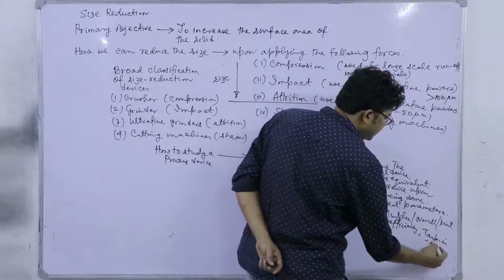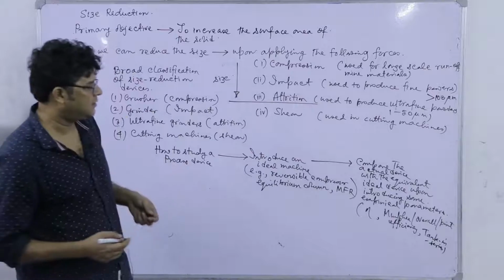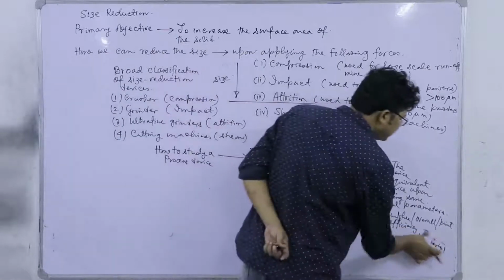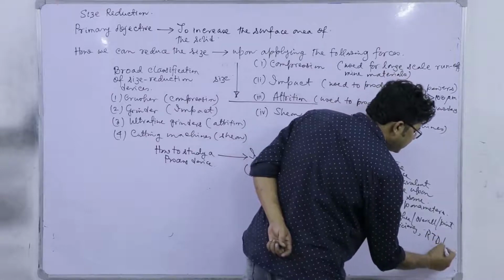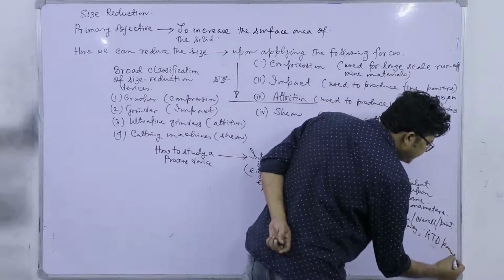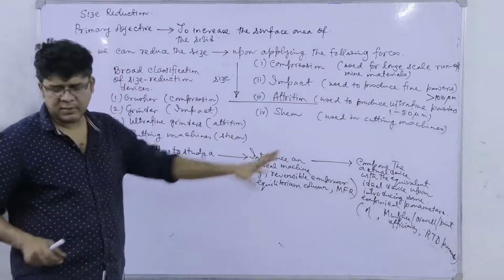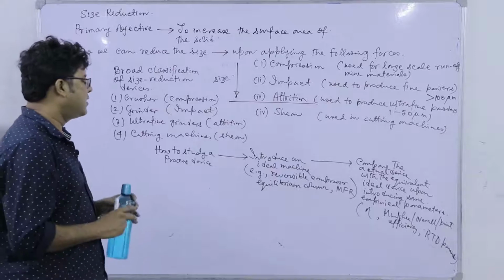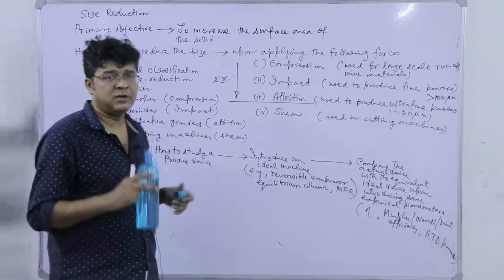In RTD studies, what we have discussed. So these are non-idealizations, or rather we should write not tank in series, it's a model. What do we use these RTD parameters for? Thereby we can have a comparison between the ideal machine and the actual machine.